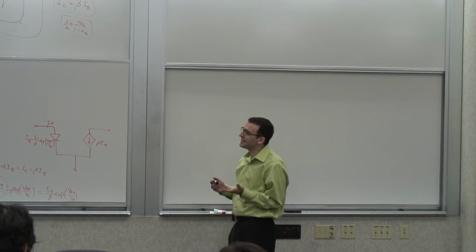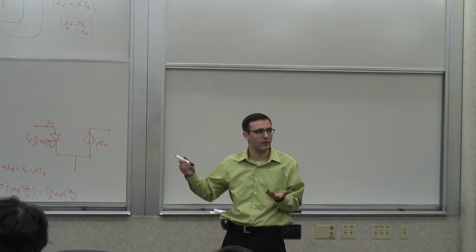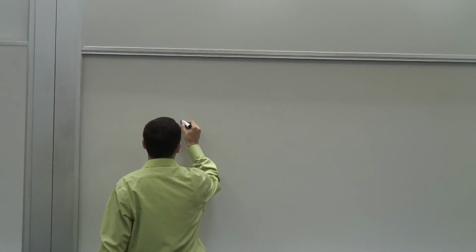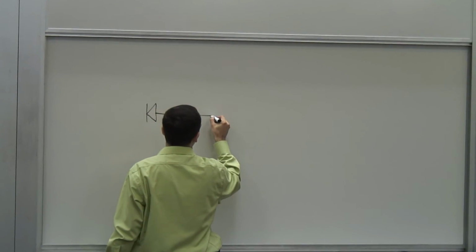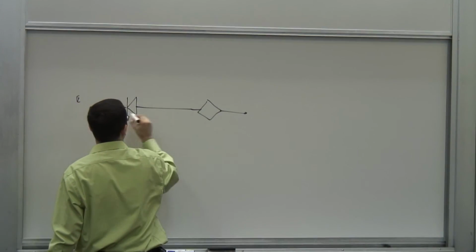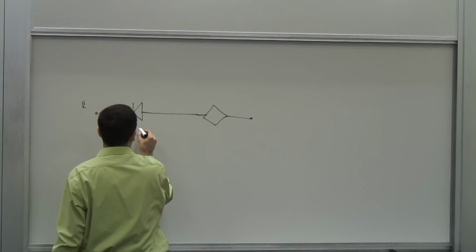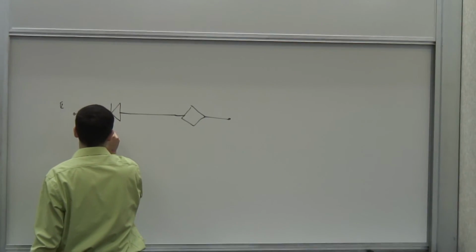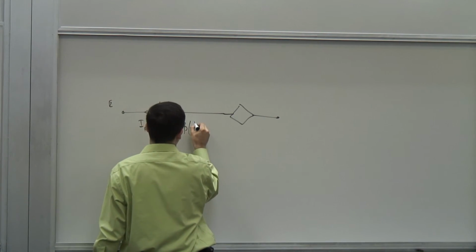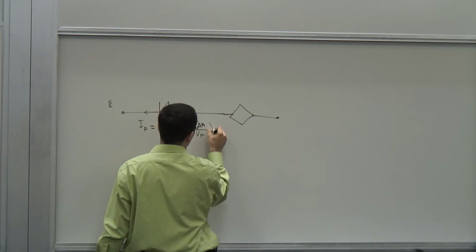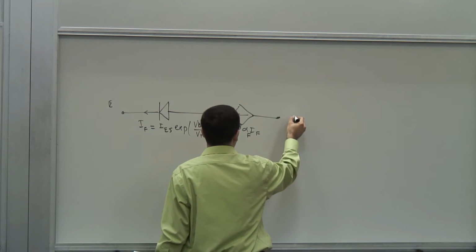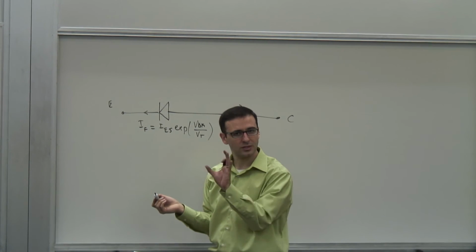Well, I noticed that I really have a second transistor, if you want to think about it. If I use the transistor in reverse mode, I have another model, just like that. So this is my original transistor model. This is the emitter-base, and let's call this IF for the forward transistor, IES e^(VBE/VT). And this is alpha F IF, the forward output. This is the collector.